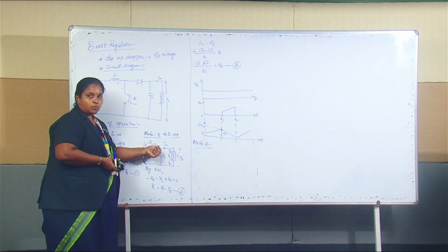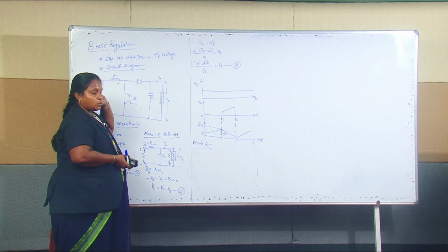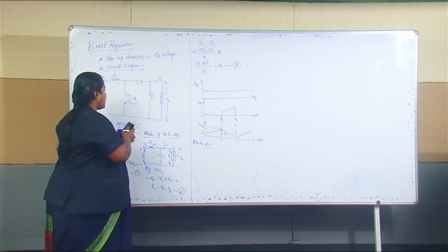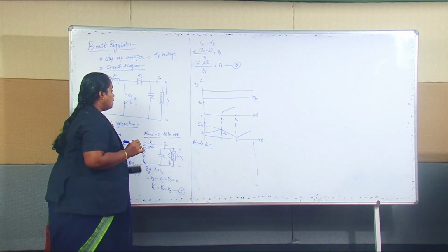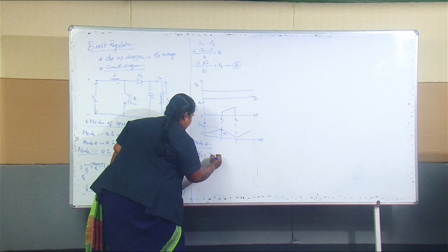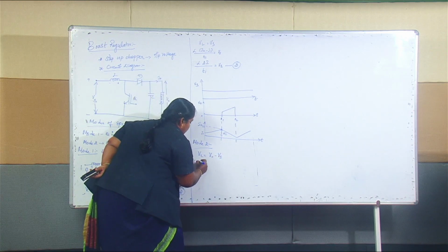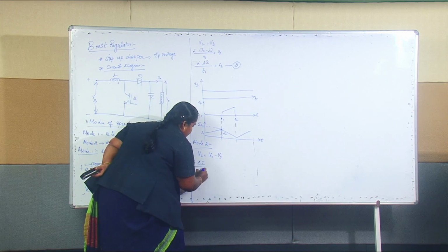This positive potential across the anode of your diode will make it forward biased. So it is in a forward biased condition. During this case, your VL is equal to, we found, V naught minus Vs. As we know, it is L into del I by T2.